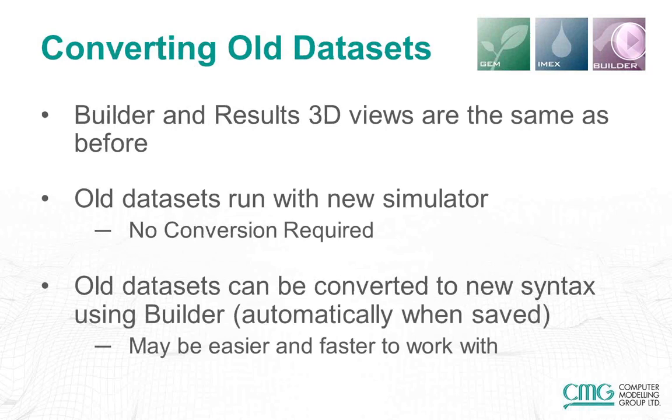If you do have older data sets that used our previous methodology, these data sets can still be used. If you open up the data set in Builder or Results 3D, they'll be exactly the same as previous. As well, older data sets can run with the newer simulator with no changes necessary to the data set. However, if you do want to take advantage of the new syntax, you can automatically convert the data sets to the new method. All you need to do for this is open up your previous data sets in Builder, and when the data set is saved, it will automatically be converted. So this may make it easier and faster to work with your previously created data sets.